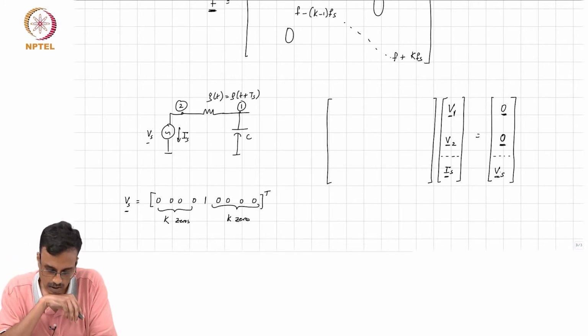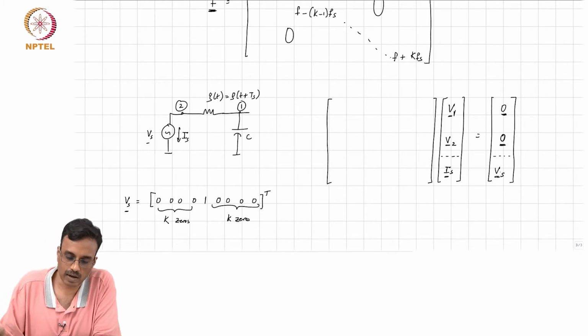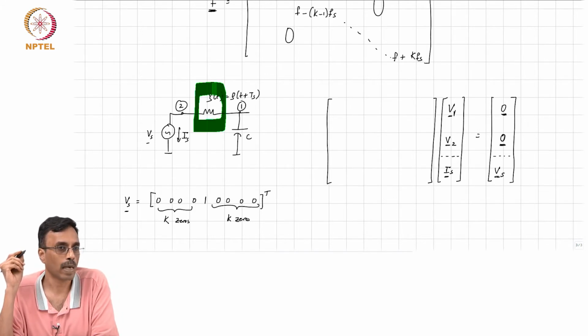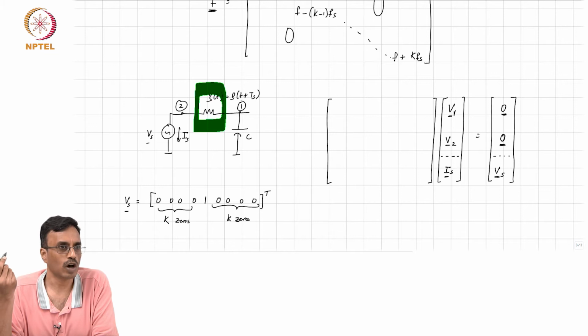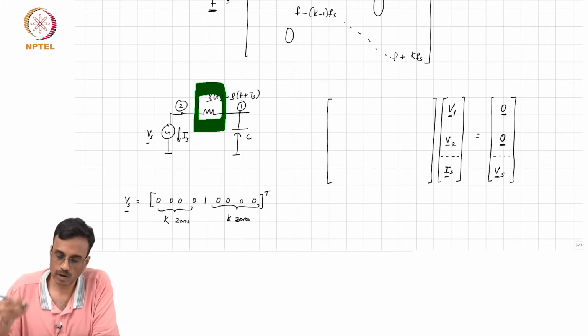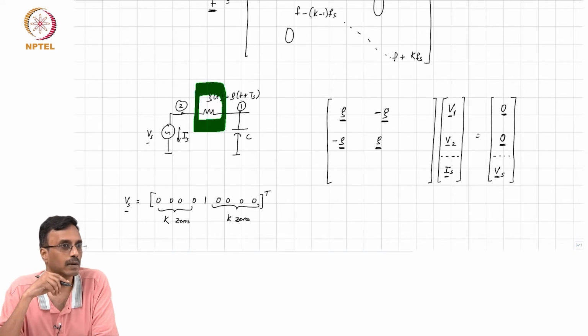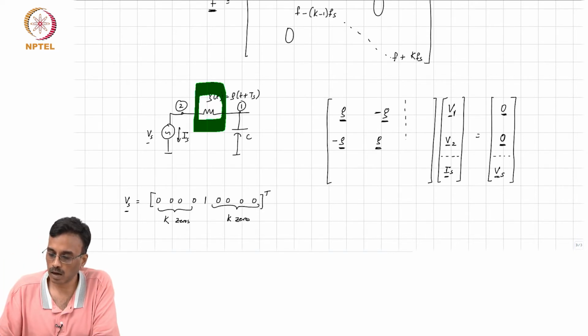Okay. And what comment can we make about, so that covers the right hand side. So, let us go element by element. What comment can we make about the MNA stamp of this guy? Between nodes 1 and 2, you now have, well, you have the G matrix and, correct, and all right.